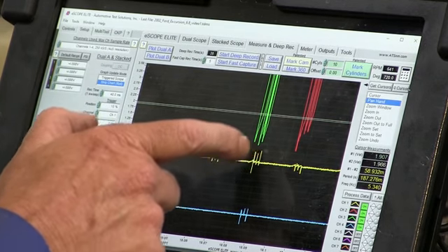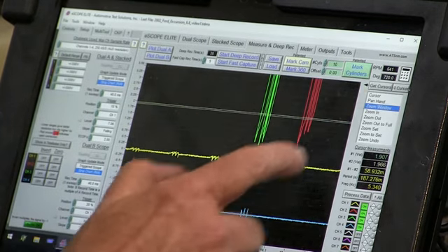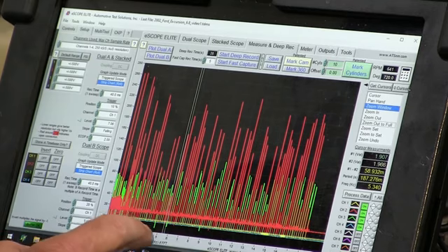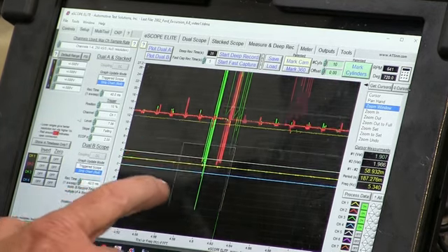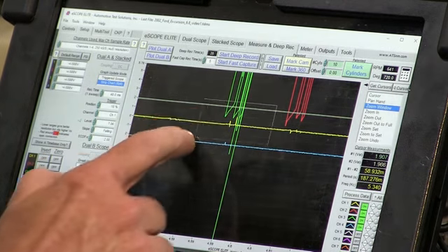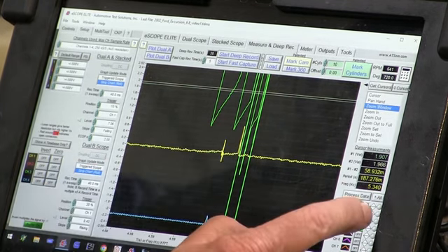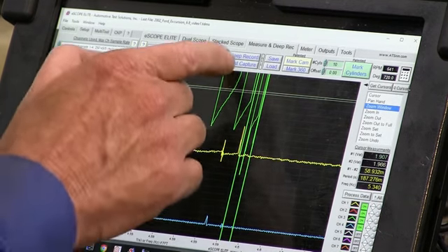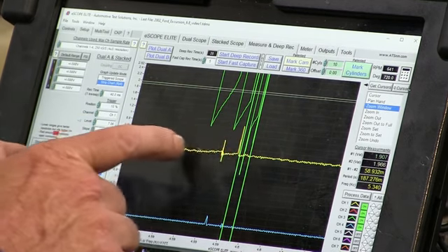So those are my coil strikes right there, and we can see that they're bigger than like 1. They're bigger than the rest of these. Look at some of these over here. That's really big. So we can see that those are riding in there and they're aligning with that fire of the coil. The coil is firing, and you can see the first strike, the second strike, they're clearly here in the sensor reading.